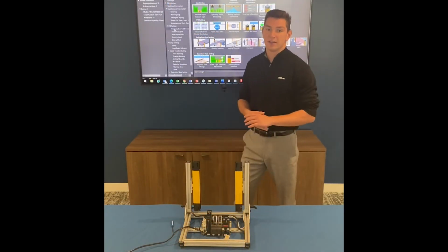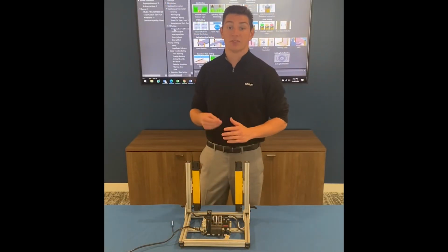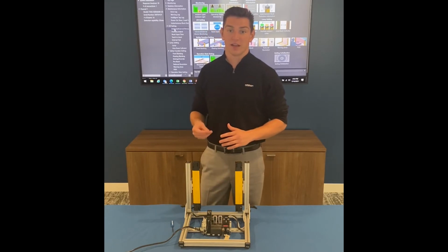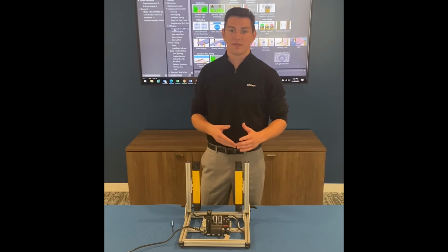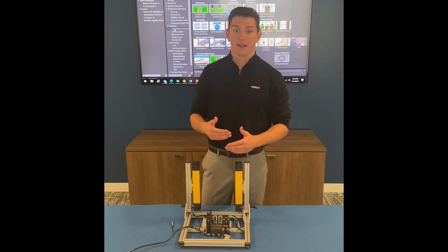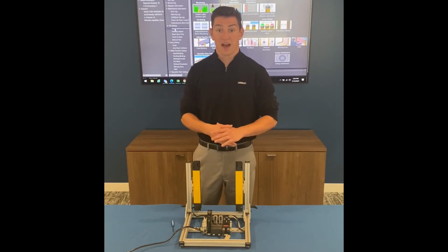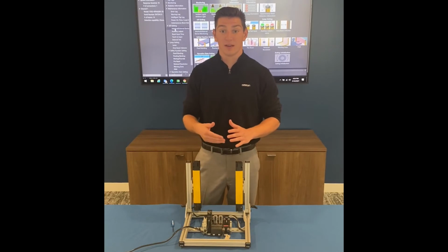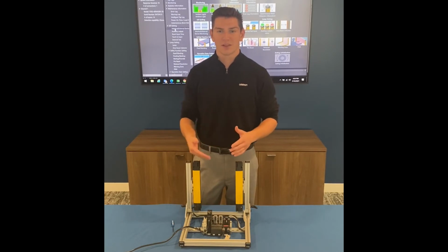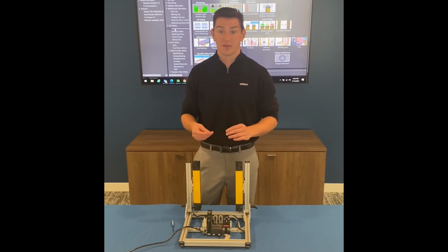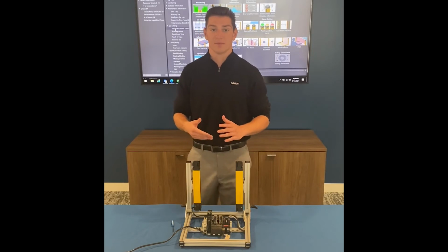Before we enable the EDM, as a precautionary act, I'm going to reset my ITAP before reprogramming it and transferring data to other light curtains. This makes the transfer of information more straightforward, and the light curtain is less likely to have malfunctions. So, to reset the ITAP, first turn off the power switch, then we're going to remove the CN1 and CN4 cables. These are the cables associated with your safety curtains emitters and receivers. Then twist counterclockwise with a little bit of force to remove the cables from the ITAP.